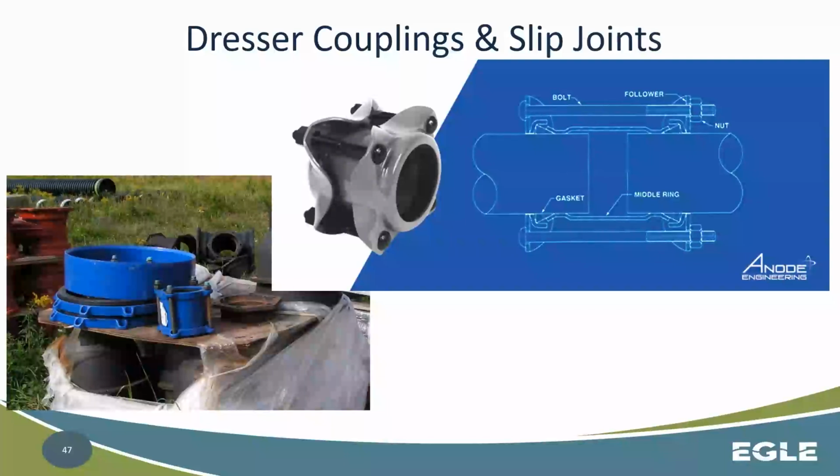It's commonly used, right? Like Kleenex or something. So this is an example of that slip coupling. Essentially what you're doing here, and what you can kind of see from this picture, I think best, in my opinion, is you have a pipe here and a pipe here that are connected, and maybe there's a gap. And that gap isn't necessarily connected. You can't force these together. It's maybe not a perfect bell and spigot kind of situation. So you're trying to connect it with this slip joint. The slip joint is going to come over the top, in between the two, and then it's going to form.